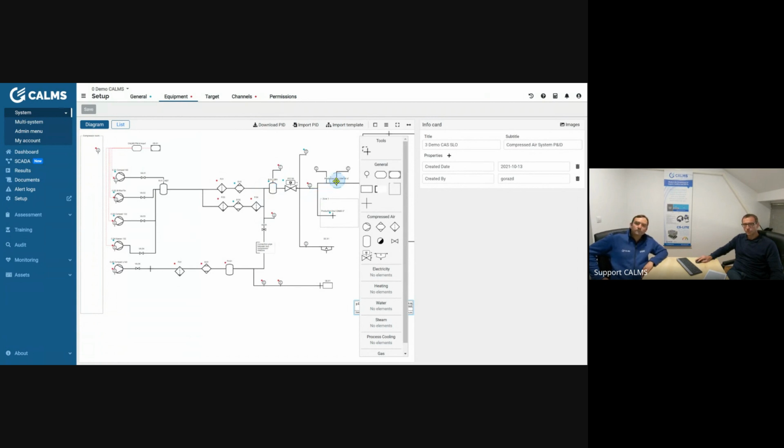And here you also have the ring in this, your first production line. And this is the location where you experience the pressure drop. That is correct. The lower one, here we don't have this pressure drop, but in this area, the top area. And you think that this is because this compressor is fresh, new, and it's delivering 7 bar without any problem, even 8 bar. This is an 8 bar compressor. Yes, that's what the guy said. No problem giving 7 bar at all. Okay, that's great to know.